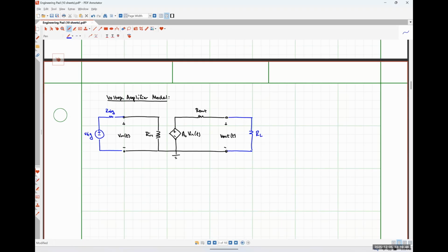It literally preserves the signal all the way through its signal path, right? So to answer your question from earlier, if I have a voltage amplifier with a very low input resistance, I'm going to kill most of my input signal at that stage, right? Or if I have a voltage amplifier with a very high output resistance, I'm going to just consume a whole bunch of excess power in that output resistance that isn't going to get delivered to my load.